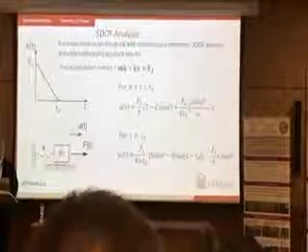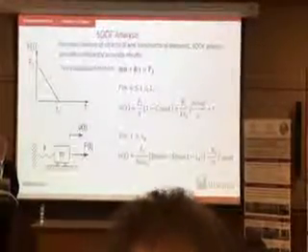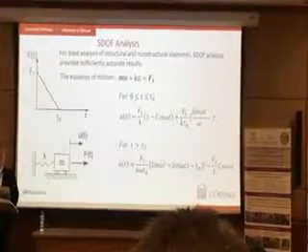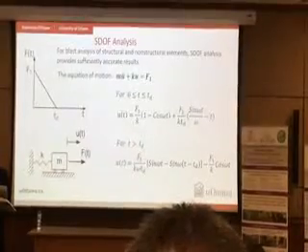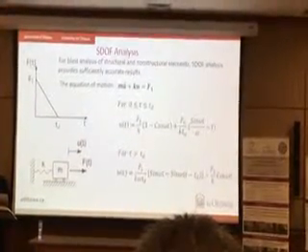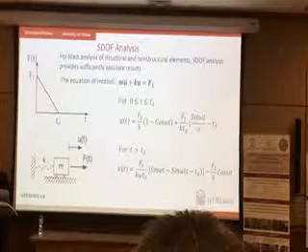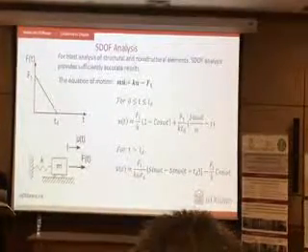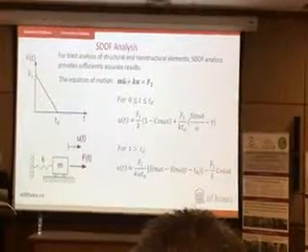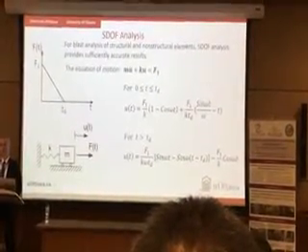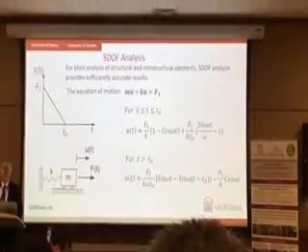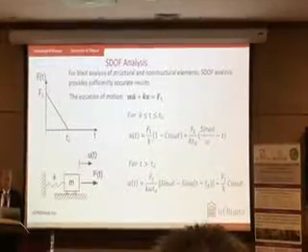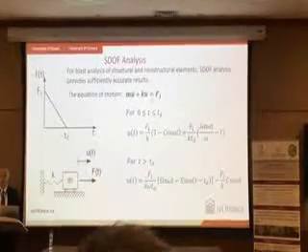Right-hand side is applied force, left-hand side is your reacting force. K times U, stiffness times displacement, is reaction. But in dynamics, you have another force, which we already talked about, which is inertia force, mass times acceleration. So the moment mass starts accelerating, it reacts to it. So there's not only stiffness of the building trying to restore building back to its original location, but there is inertia force also helping. So this is the equation of motion.